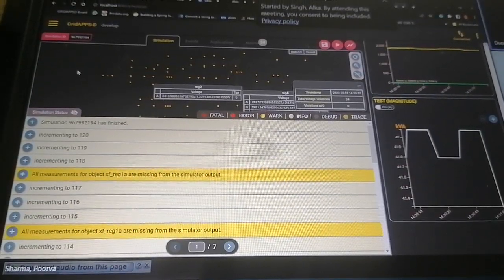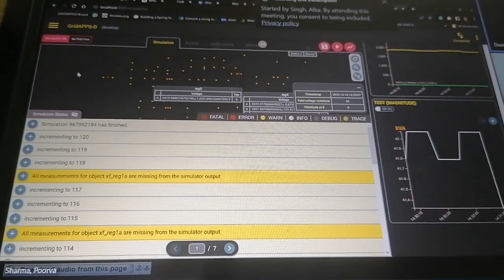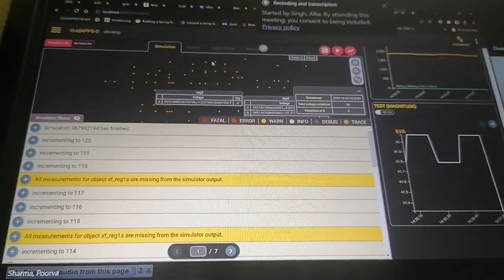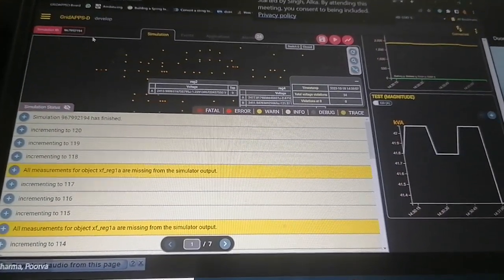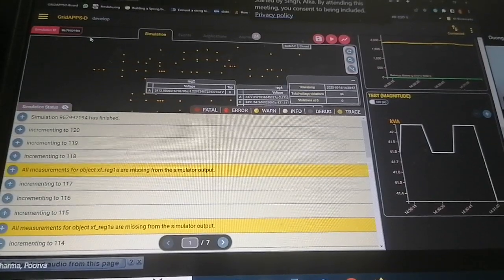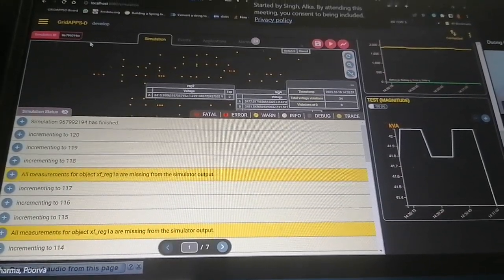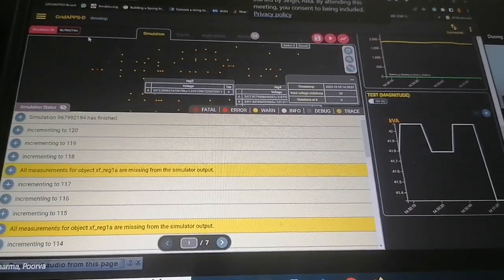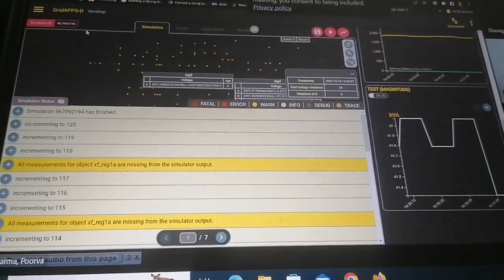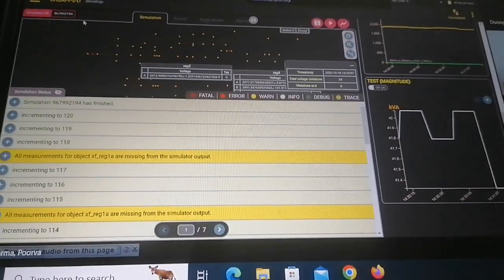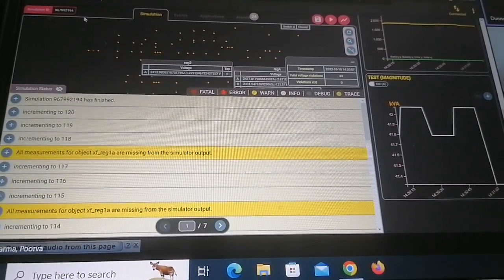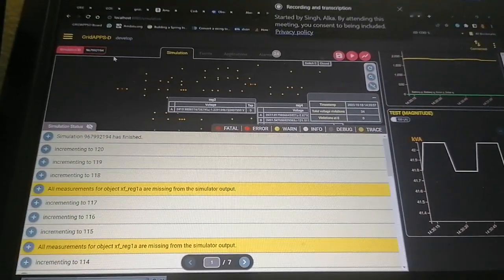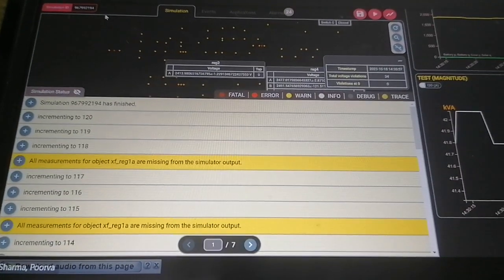So this simulation is basically where we provided GridLAB-D with the IEEE 123 distribution model and said, given this load profile, start at this particular time and run it for 120 seconds. It does not have any specific purpose other than showing it for a demonstration. For different purposes, you can use different types of simulations based on the projects we are working on, which is why I'm giving you the examples.